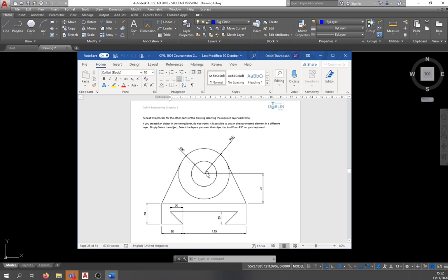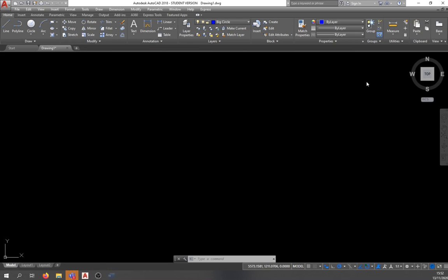So there we're going to go. We're going to do this first of all. I'll just do the circles first, and then we'll stop there. Let's close the notes. Our dimensions for the circles are actually on the notes. So I'm just going to bring up the circle, and we are given the dimensions in the radius. So drop the menu, center radius circle. Just click anywhere on the screen.